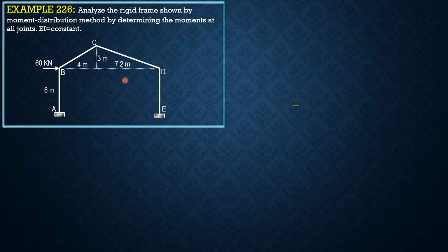The technique here is we first imagine that DE is fixed, held vertically straight, and we apply the sideway delta 1 at B and express the sideway of BC and CD in terms of the sideway displacement at B. In the second part, we hold AB vertically straight, with no sideway, and due to sideway at D, which is denoted delta 4, we can express the sideway displacement of CD and BC in terms of delta 4.